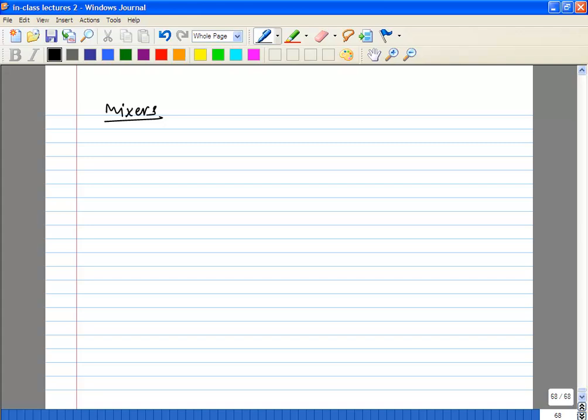That will add a pole. Sure, but it will be very far away. You are trying to minimize RB, so it doesn't have that much impact. Once you give a ring, the resistance and the capacitance both will be very small, because you are giving a local contact for your bulk.